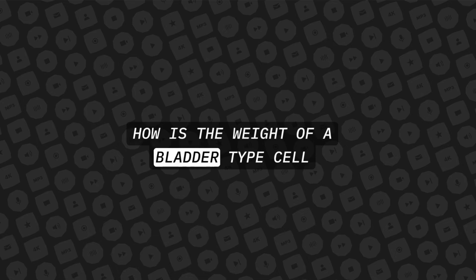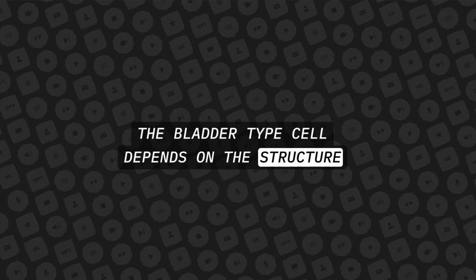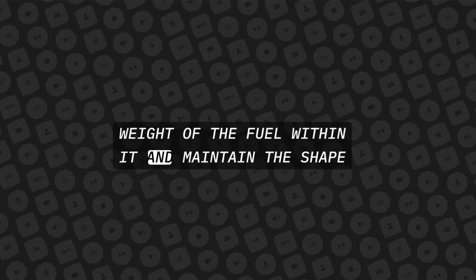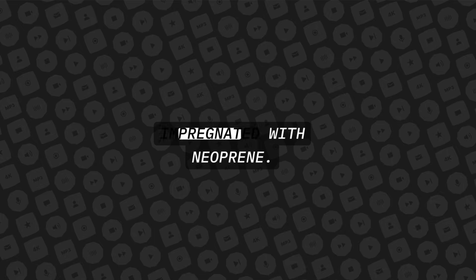How is the weight of a bladder type cell supported? The bladder type cell depends on the structure of the cavity in which it sits to support the weight of the fuel within it and maintain the shape of the cell. They are made of either rubber, nylon, or impregnated with neoprene.